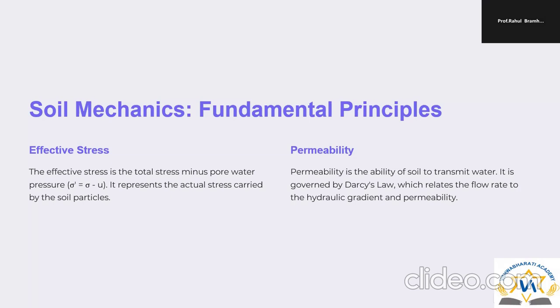In effective stress, we are finding out the various loads which are carried by the soil. Effective stress is the total stress minus the pore water pressure, and it represents the actual stress carried by the soil particles.